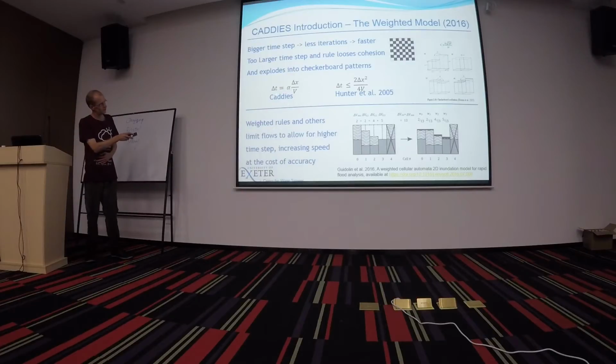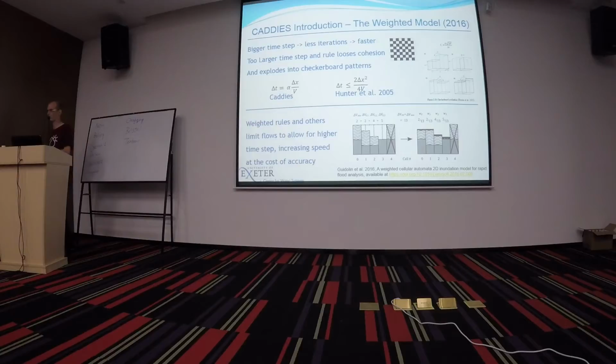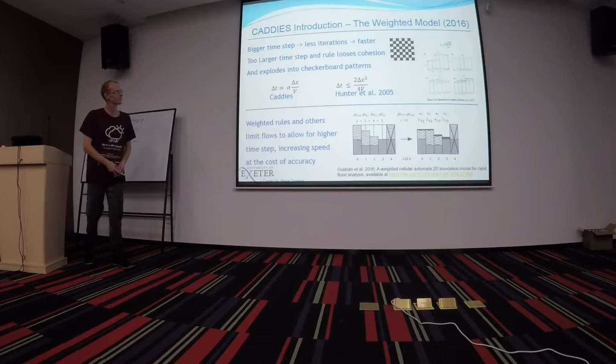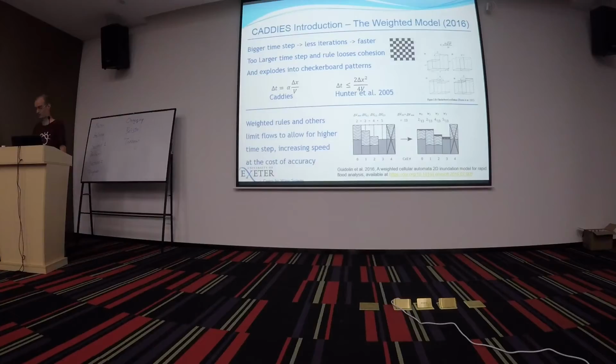Our system uses this equation here to calculate the time step, which is effectively based on the cell size and the velocity at the time, and a relaxation parameter between 0 and 1. So this means we can turn it down. Other systems use a slightly more complex formula, but that would create more complexity in the actual model as well. This condition is called the Courant or Courant-Friedrichs-Lewy condition, which is supposed to be the condition at which oscillations will begin.